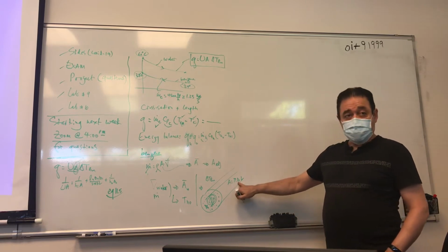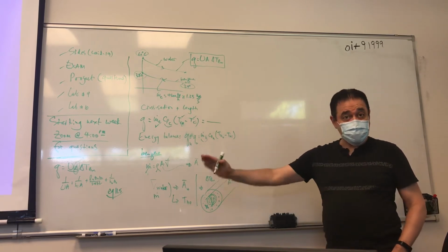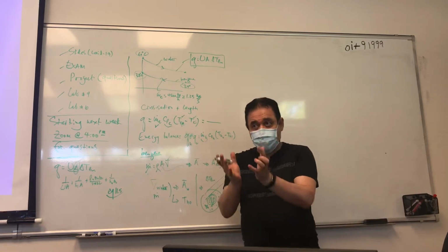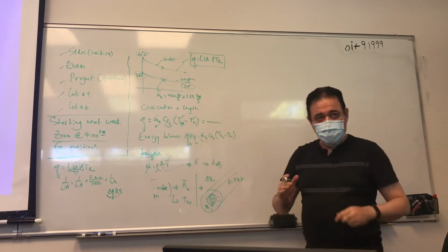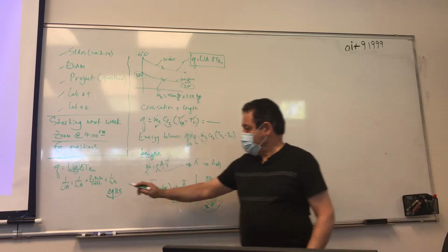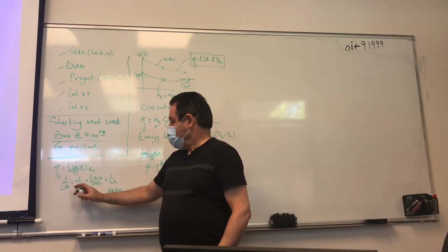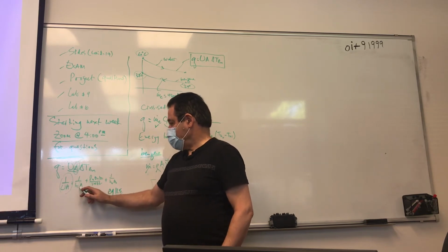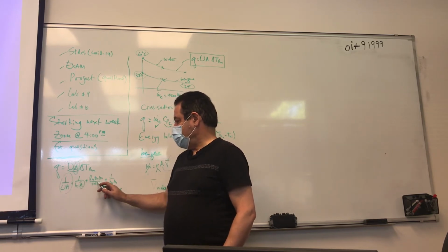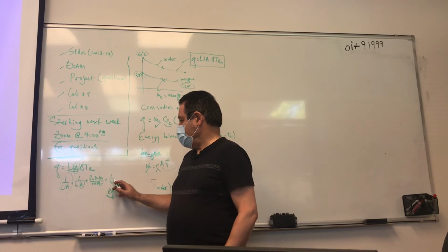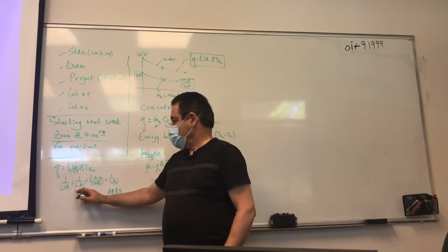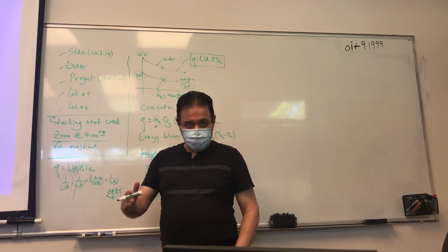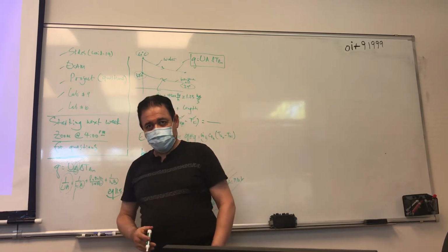Now, do you know that DI? Yes, because you have selected already previously what is flowing where, right? So you know the stuff. So to find what 1 over UA is, or UA, since the area here is a function of L, there is an L here. So your problem is really to find what HI is and what H out is. That's the part that you're missing, right?